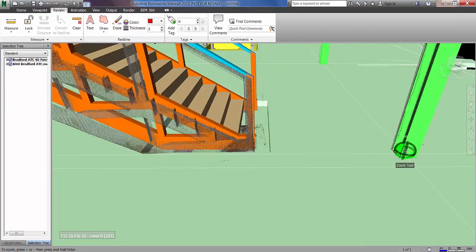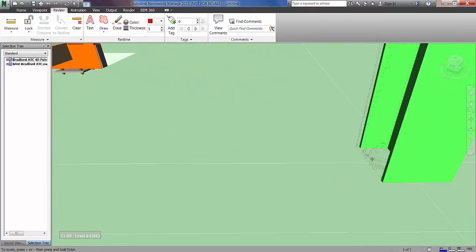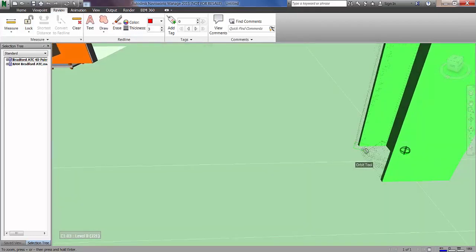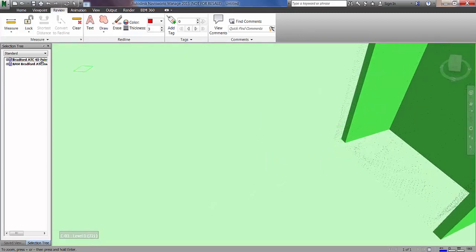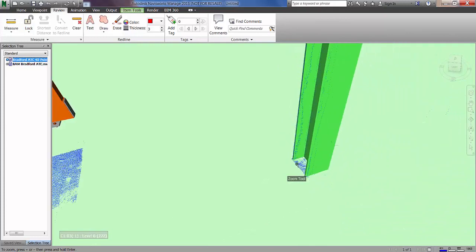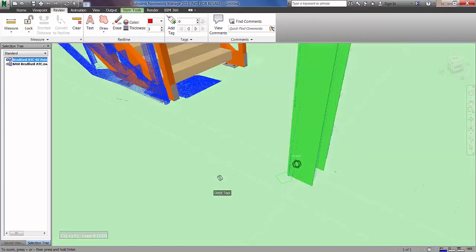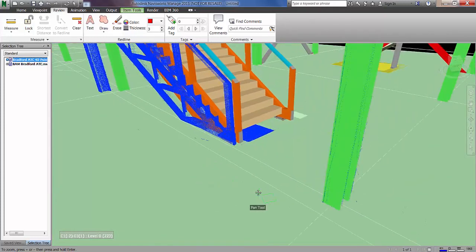So we'll just zoom into the particular column that we just used. I'm just going to update that transformation again using an additional measurement just to close out any minor inaccuracies. So I'll just take this measurement here now. I'm going to highlight the point cloud in the structure tree, and I'm just going to go transform selected items to move that across.